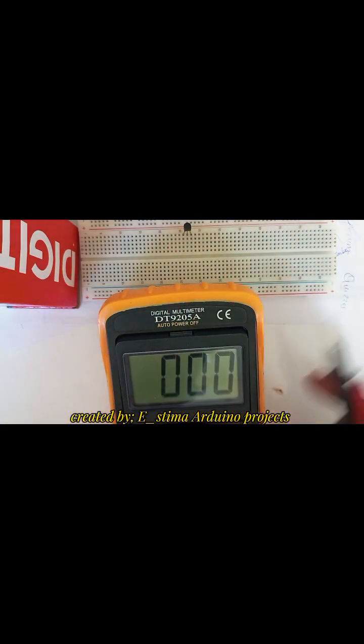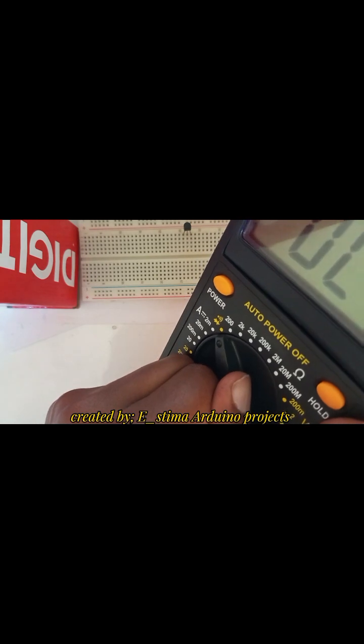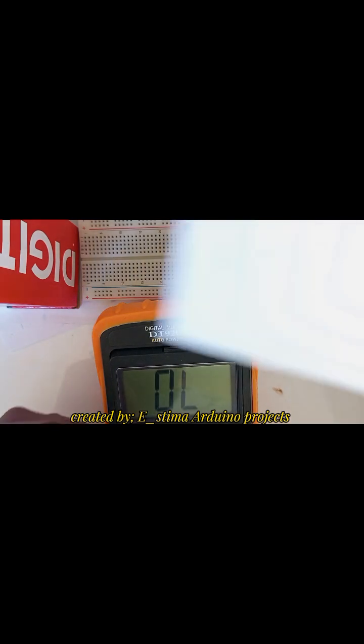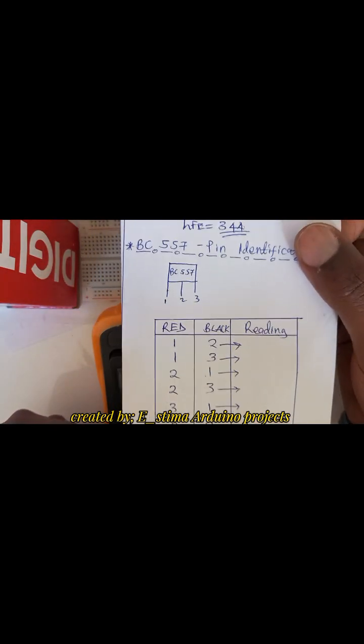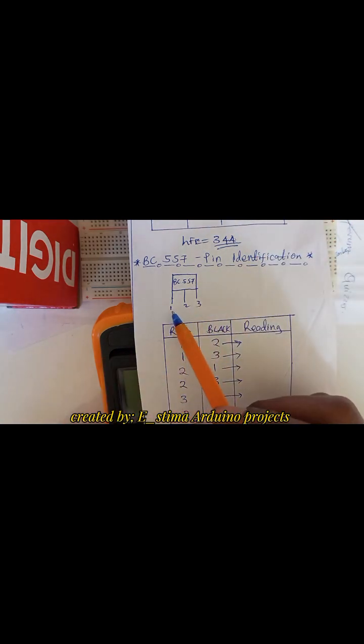Here are my probes. I set my digital multimeter to diode test, where we have diode and continuity test. This is my table for BC557. With the transistor's flat side facing me, the farthest pin to the left is 1, then 2, 3.